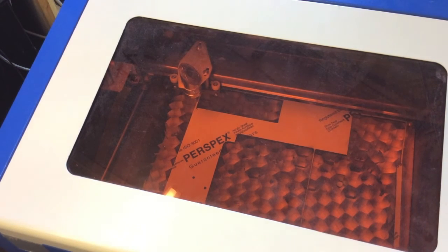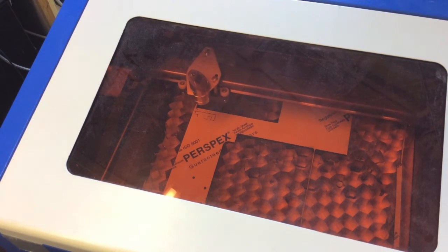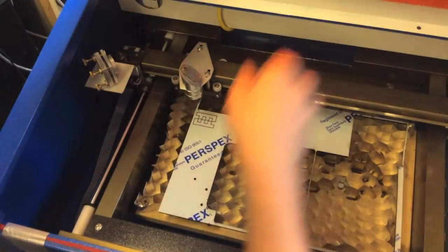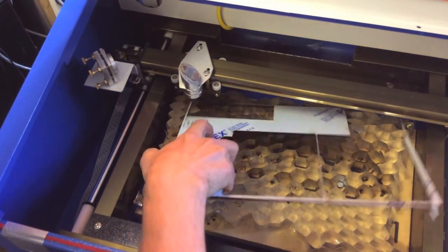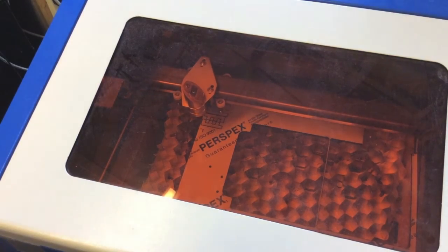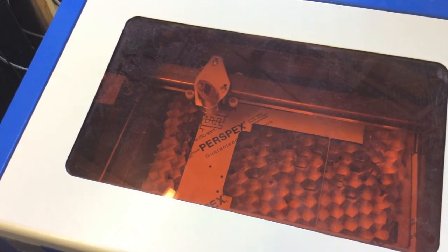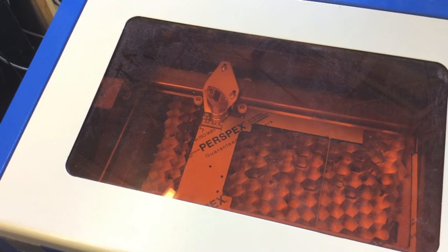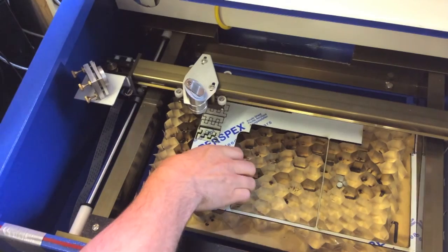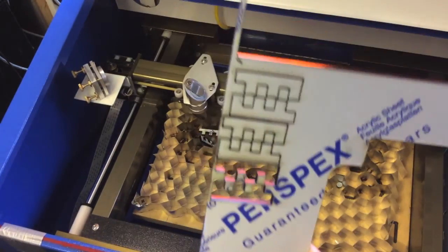So this was my first cut with the G-code that came out of the machine. I was cutting very fast just to see whether it could do it or not. But on this one I didn't actually set the beam width high enough, so it didn't come out at all. This was a cut at 10 millimeters a second and using a slightly higher power beam. This time the pieces did actually come out of the acrylic okay.